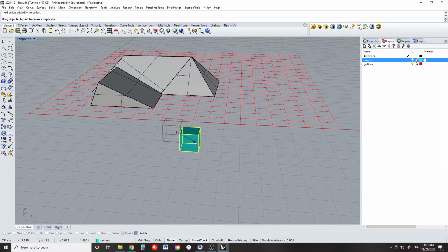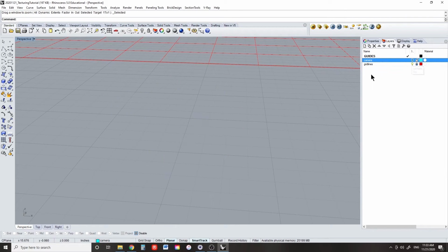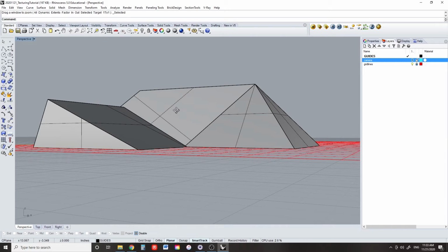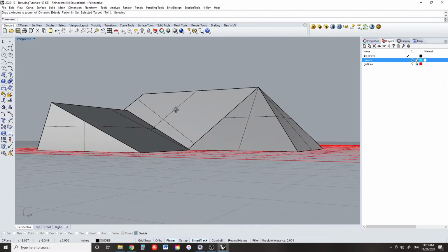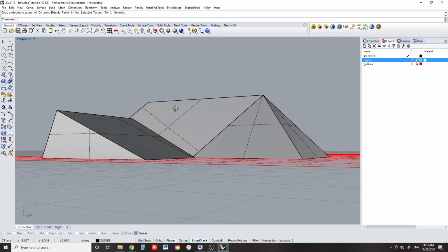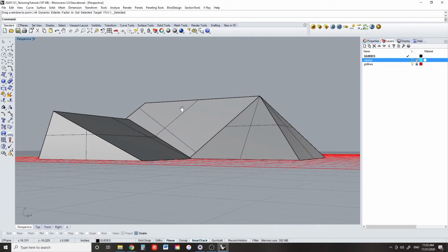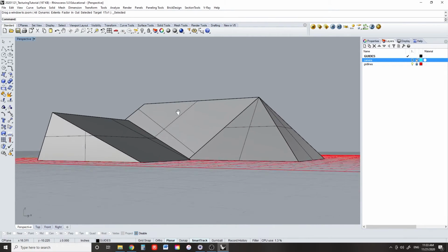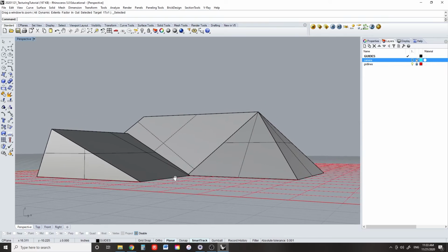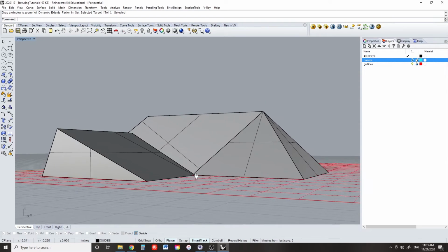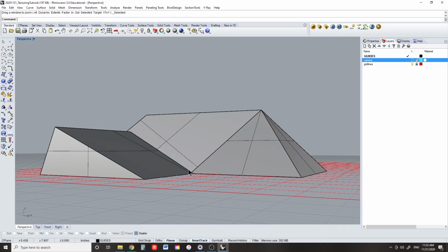Then finally, by hiding the cube, I can now see what the point of view of my scene is from the cube's perspective. So if I imagine that I am this little cube, I put myself in the scene where I would like to see this geometry, zoom into it, and then I've got my point of view. After you've hidden your placeholder, you can always make small adjustments with pan or orbit.